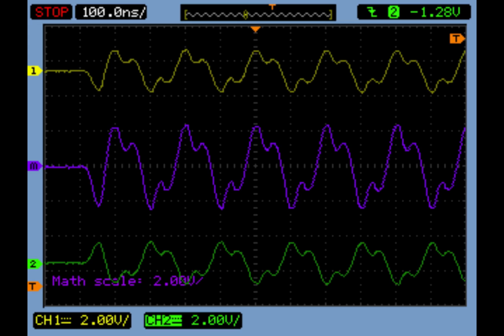And then we start to send our preamble, so our sequence of ones and zeros. So you can see if you look at the purple trace in the middle, we have a rising transition on the sample point. So we're going from the negative voltage state to a positive voltage state, so that encodes a logical 1. And then at the next sample point, we've got a transition from a positive voltage to the negative voltage, so that encodes a logical 0.